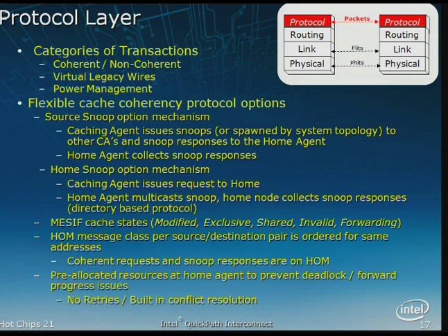I think most of you have already heard that at the protocol layer, Xeon 5500 is a source snooped based coherency protocol, not a home snooped. We also do have home snoop ability in the QPI spec. I'll get to the caching agents, I'll skip that to the next one. And then the protocol for coherency is a 5-state protocol: modified, exclusive, shared, invalid, and forwarded.